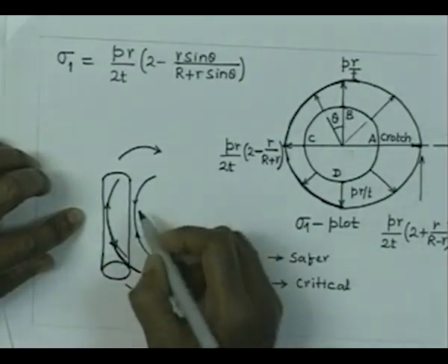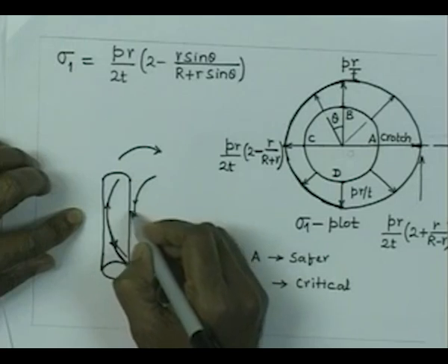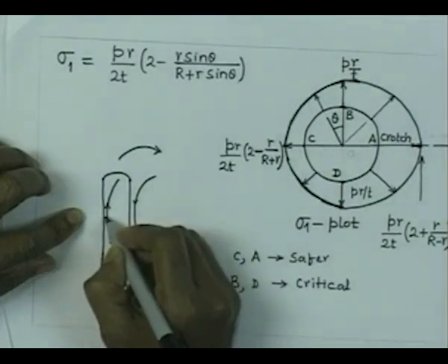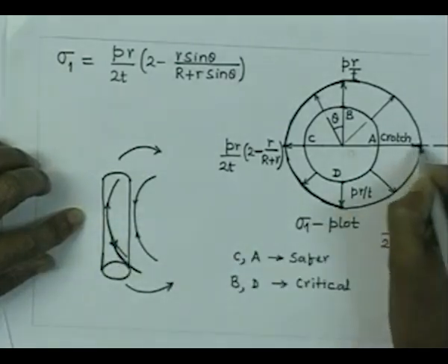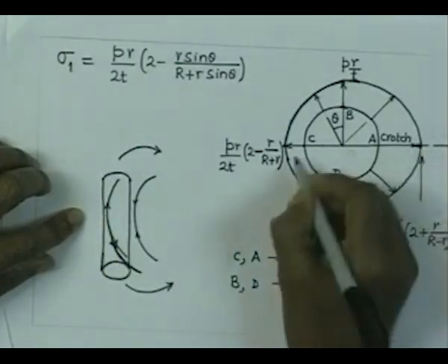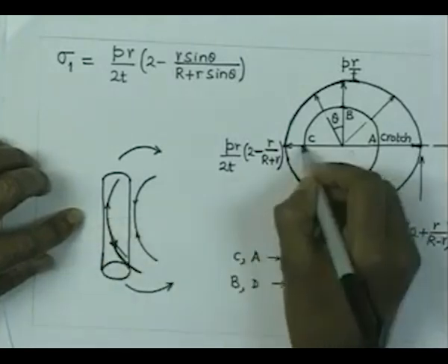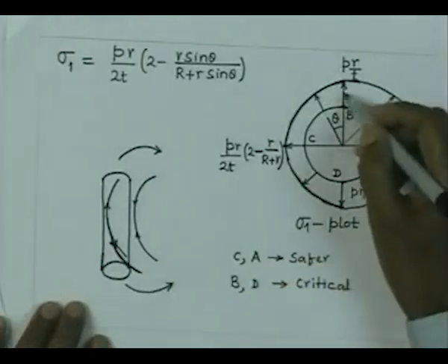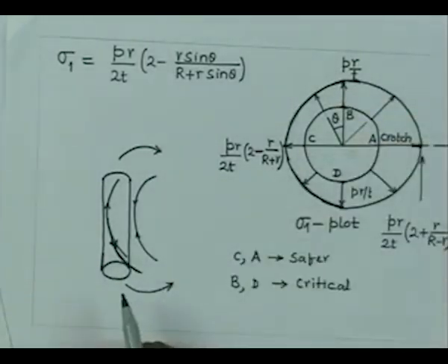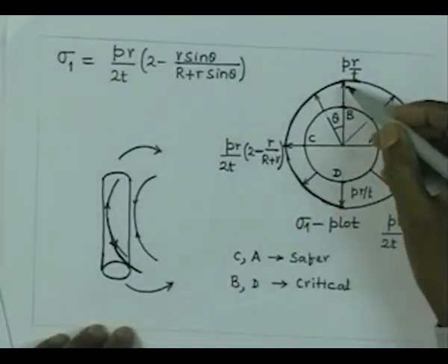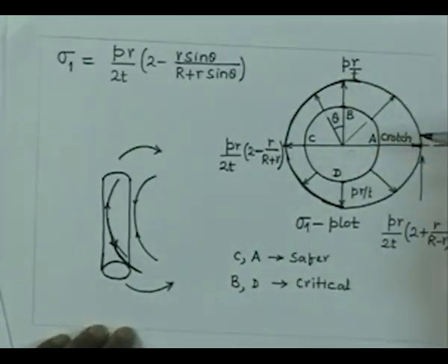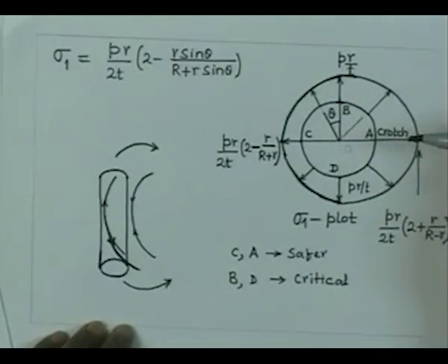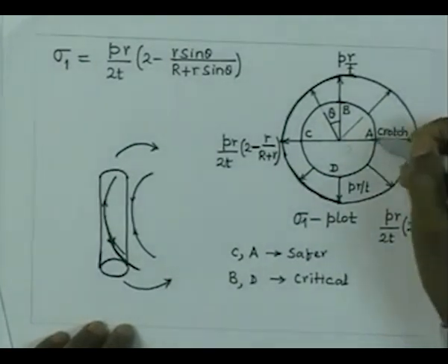So, therefore, during the process of manufacture itself, you are going to find the wall thickness to be higher here, and here it is reducing. That thickening of the wall will take care of the extra stresses here, and here it is thinning down, and therefore the stress is reducing. So, naturally they are taken care of, whereas these points are not really going to be affected to that extent, and therefore, for such shells or configurations, these are not the critical locations.